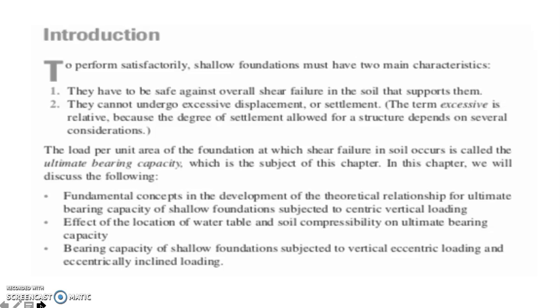So basically, the concept here is the ultimate bearing capacity for shallow foundations. In foundation engineering, we have what we call shallow foundation and deep foundation. When you talk about shallow foundation, meaning this is your footing, the foundation depth is not greater than 3 meters. Greater than 3 meters, the depth is now considered as deep foundation. So basically, this is ultimate bearing capacity for shallow foundation.